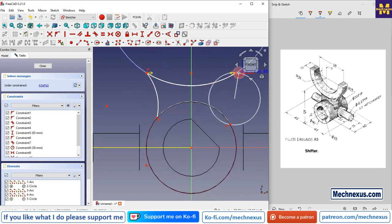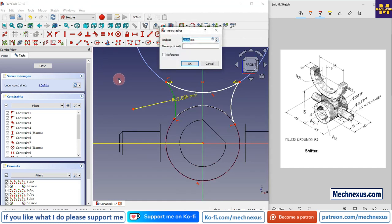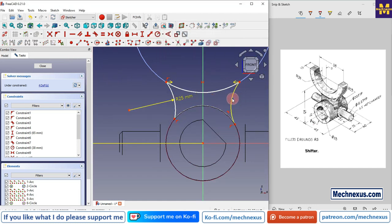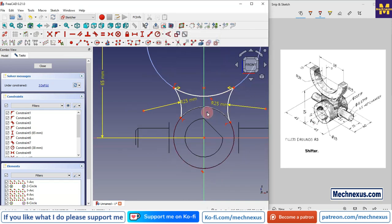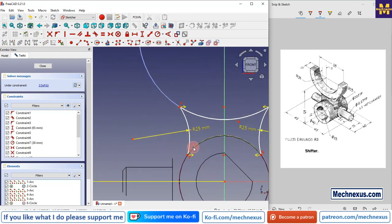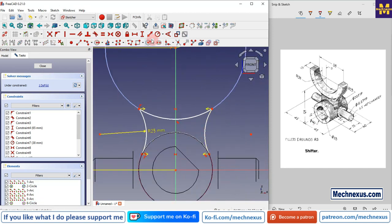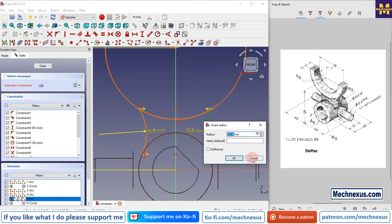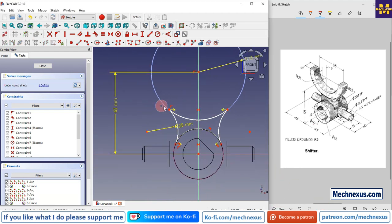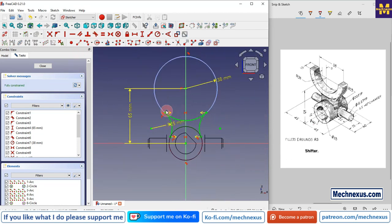and also a 3-point arc at this side, and this radius is of R25. And this axis, and now we will select this arc and this arc and add the tangency, this arc and this arc and add the tangency. Select the radius dimension, and it is already 25. Now if we see here is a coincidence, but there is no tangency, so we will add the tangency constraint, say tangent, and now our sketch is fully constrained.